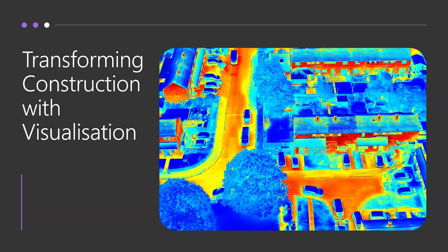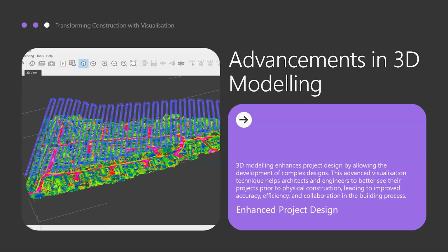But for instance, like this job, if you were trying to thermal image the whole of the estate, it would have taken weeks and weeks and weeks. With the drone, we did 3 nights of scanning, but the actual maps were made in, I think, about 2 hours of flying. And then I think half a day of crunching the data, putting it through PixPro, who then created their maps. We've got a 3D map and a 2D map. But yeah, this is from the 3D map.